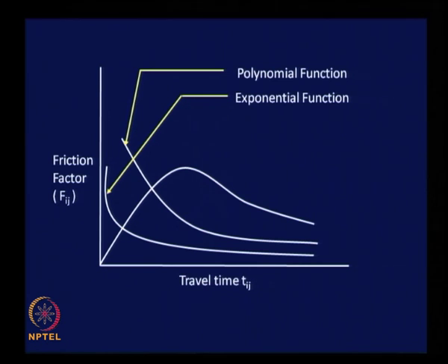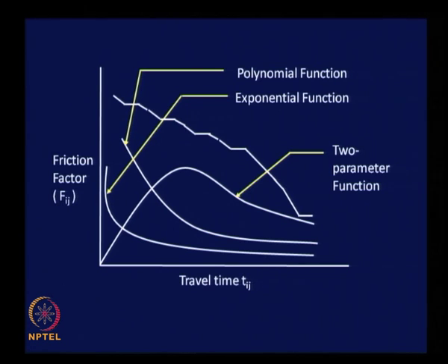And the BPR method will result in this kind of curve, broken curves. That means each piece will have a different functional form. Parameter values will be different for different stretches. Okay. So, the slope of these bits of lines varies depending upon the travel time range in which it is falling.